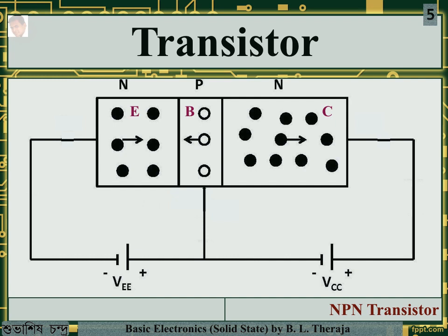In a transistor, the base region is doped lightly and holes are lesser in that region. Therefore, the hole diffusion current is less than that of the electron diffusion current. The total current consists of the hole current and the electron current, but practically it is just the electron current flowing from the emitter to the base.